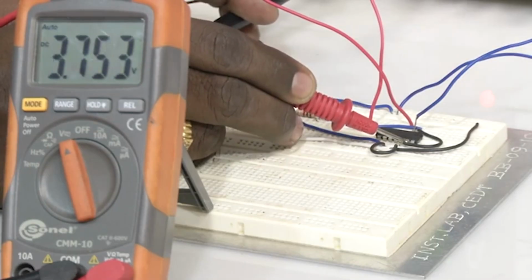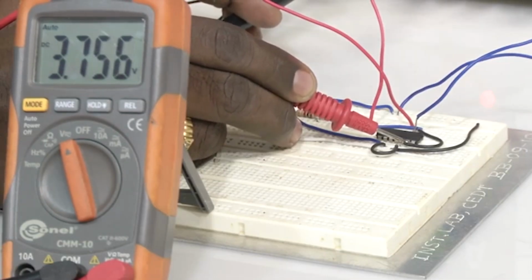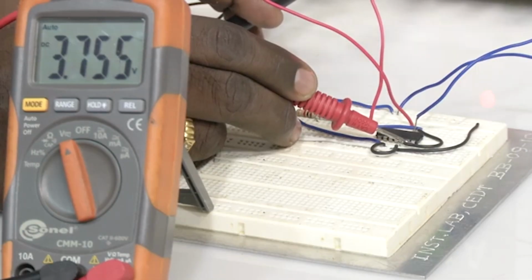Since the plus VCC is connected to 4.9, and when you recall the saturation voltage of your operational amplifier, the saturation voltage will be always lesser than that of your plus VCC. Since it is of 4.9, somewhere approximately 5 volts, right, the value will be lesser than 5 volts. So, somewhere it is showing 3.7. So, if I increase plus VCC value, then even that value will change, right. So, 3.756. So, anything greater than 2.5 will be 1. So, I can say this C1 output is 1. What about C2 and C3?